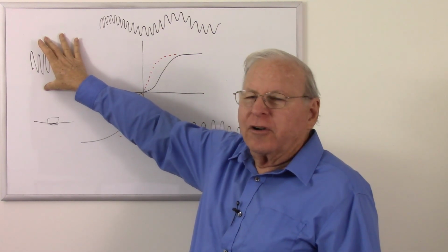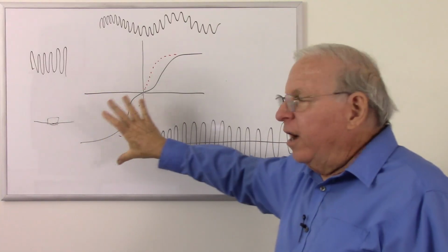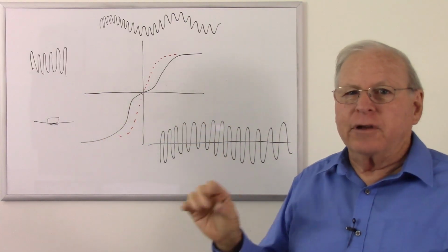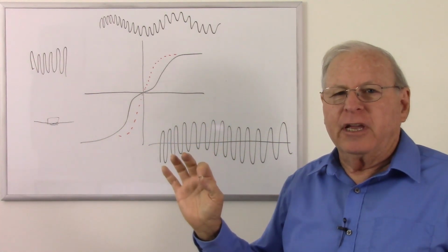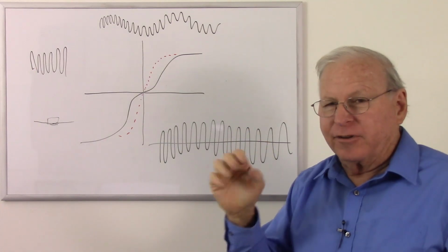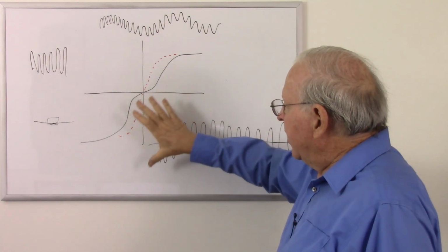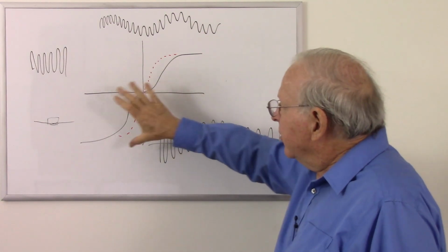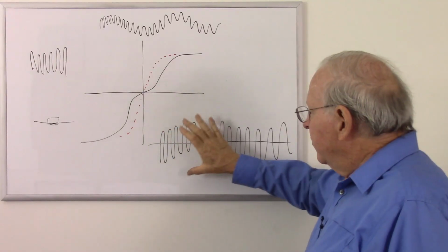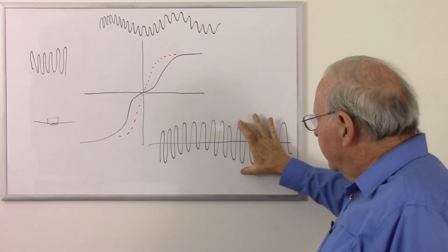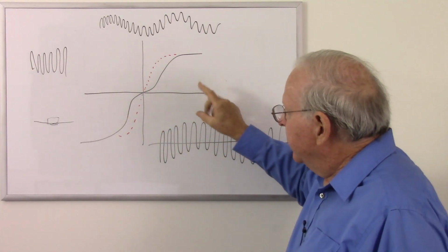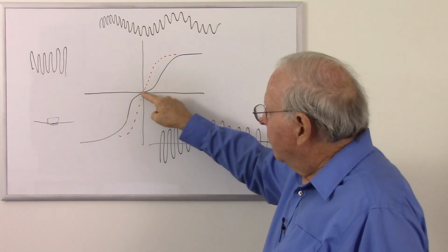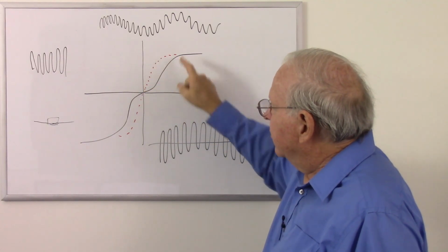Seems like 100 kilohertz is very common. There's no way the tape can record such a high frequency. We'll talk about frequency and speeds and tape gaps in just a moment. But since that can't be recorded, it basically erases the tape. But once again, we get a little bit of an offset from this audio signal that's put on top of it that causes our erasure to end up following a nice linear curve.